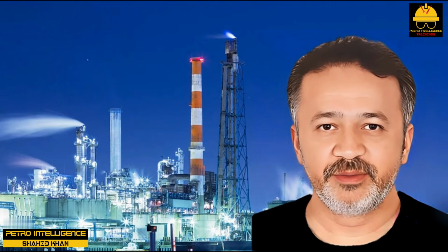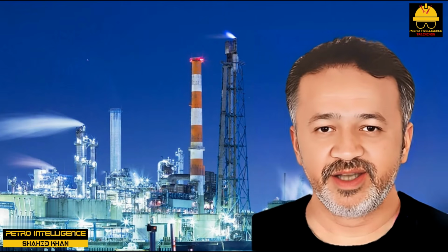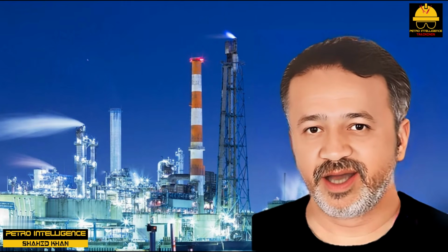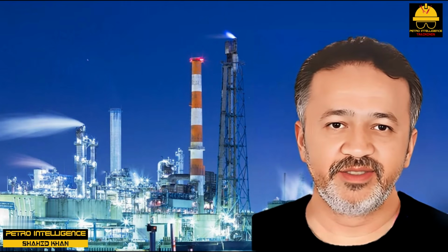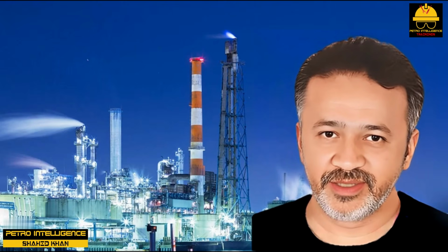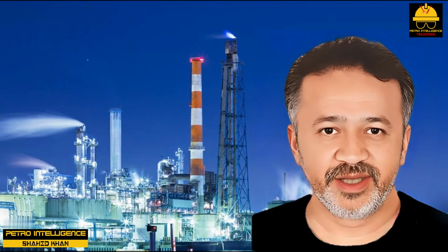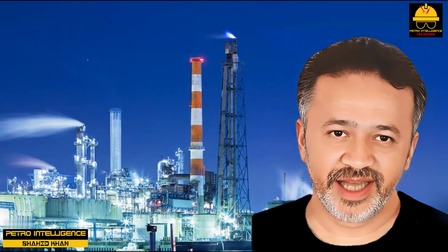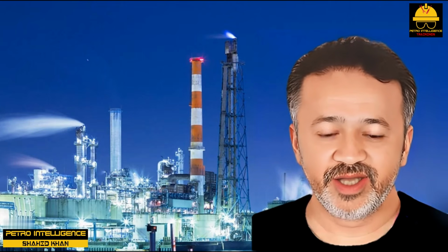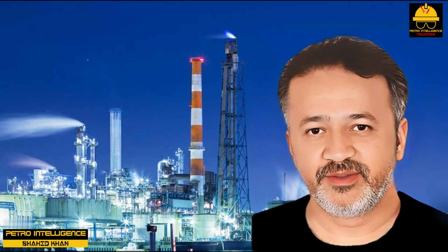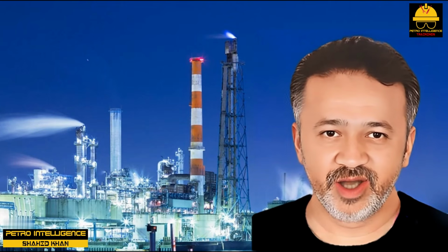Adjusting the refrigerant composition does not significantly affect the amount of horsepower needed to provide a fixed amount of cooling at a certain evaporator temperature. This statement is true even if the type of refrigerant used is changed completely. Propane, isobutane, freon, and ammonia all have roughly the same refrigeration efficiency. That's all, gentlemen.